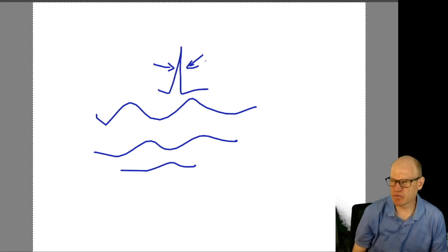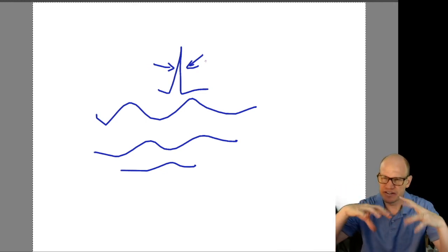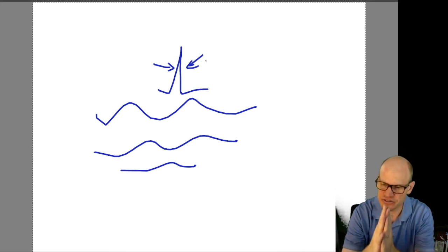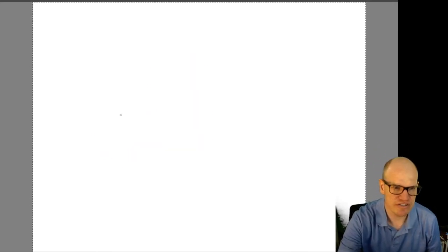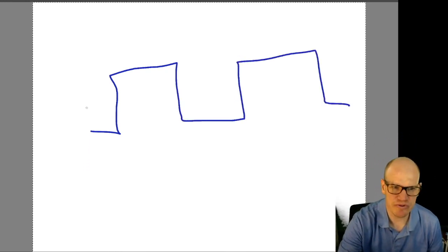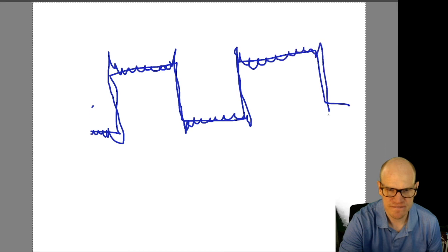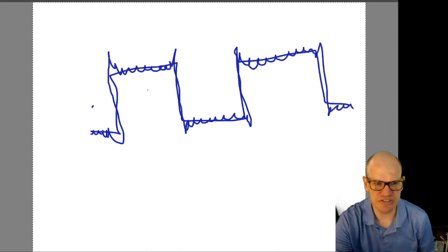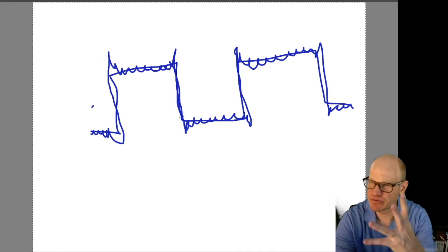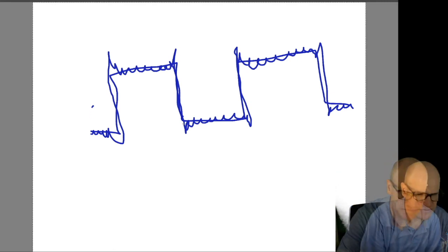So when you're in a signal processing class, you might have a square wave or a sawtooth wave. And if you want to build up a sawtooth wave, if you have an abrupt feature, like a square wave from a signal generator, as you build it up from different lower frequency sine waves, you're going to get something that goes like this, and it jumps up from the Gibbs phenomenon. It overshoots. So this is a series of contributing frequencies, and the sharper the feature, the more high frequencies you have to add, and the more high frequencies you have to add, you're basically expanding it out into the continuum, into all possible frequencies.